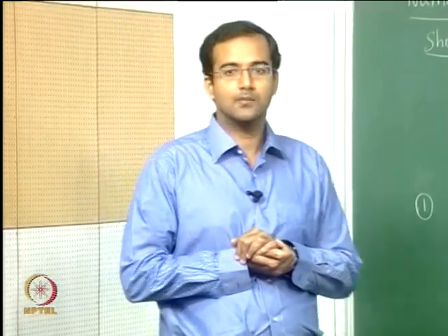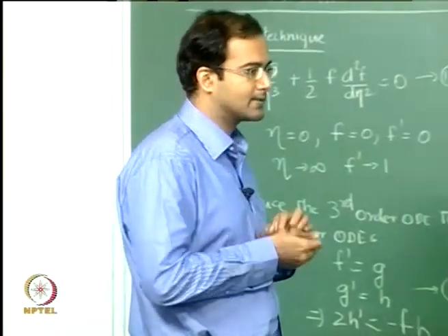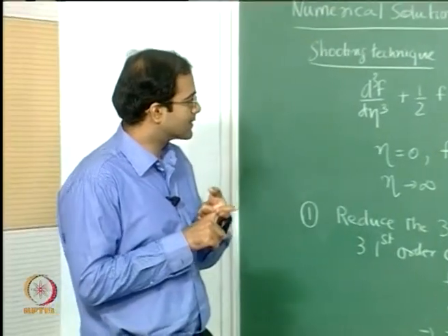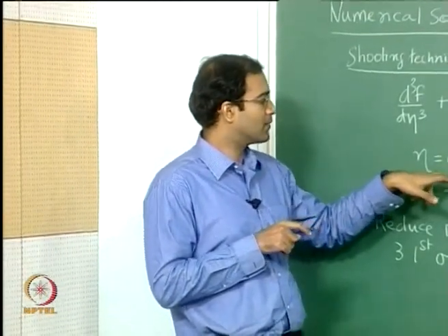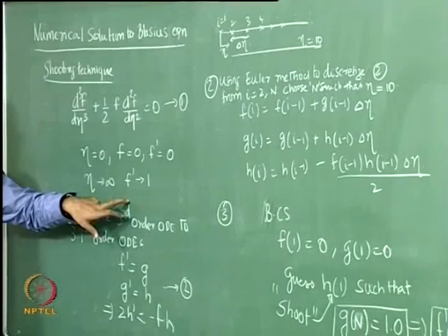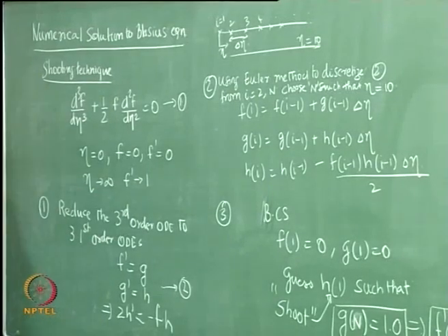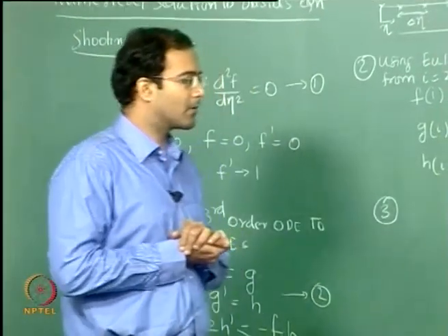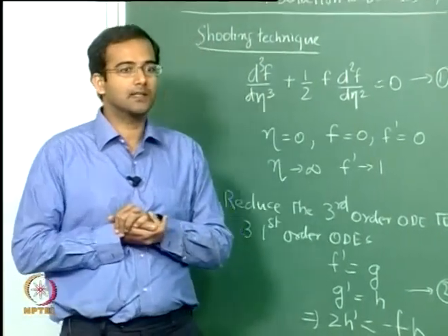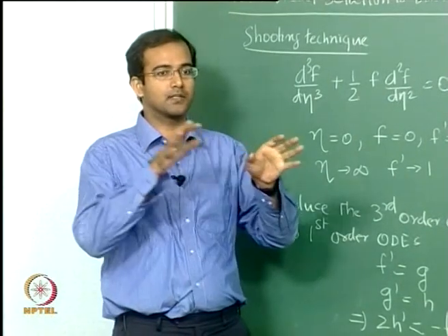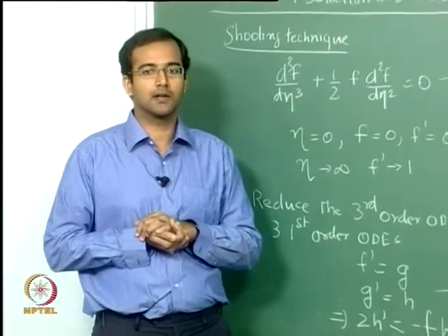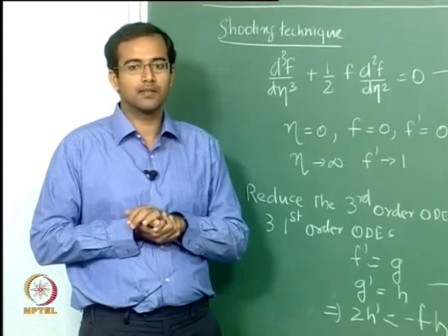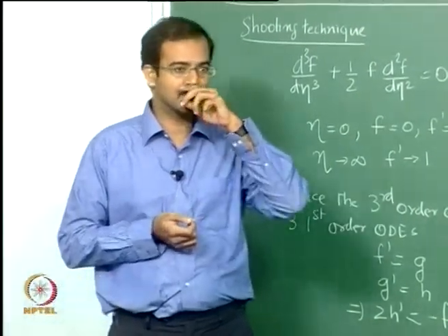So that is an asymptotic expansion he did, and then he matched the coefficients of these two series subject to these 3 boundary conditions, and therefore he finally calculated the slope at the wall, that is f double prime at 0. So once he got the slope, all the coefficients in that series were a function of that slope, and he calculated the f basically. Okay, so that's how Blasius did it, and we have discussed that in the last class.